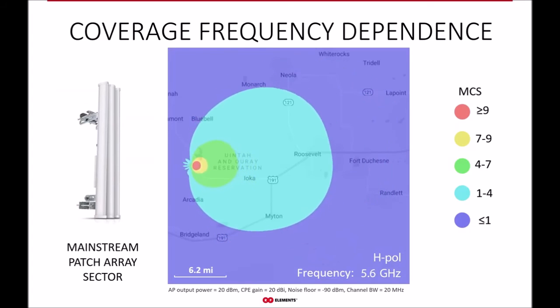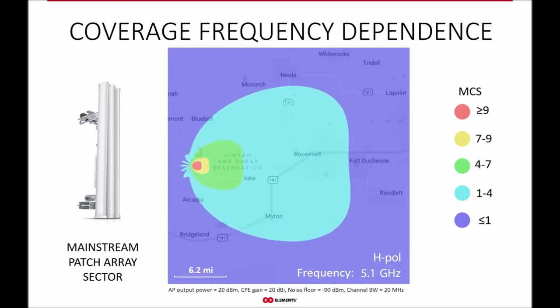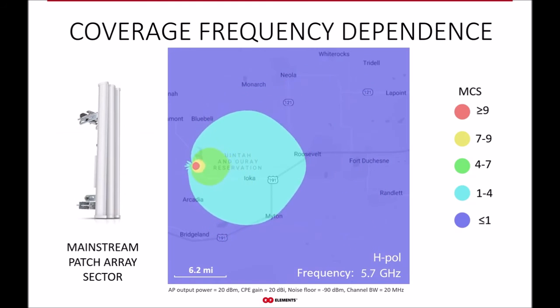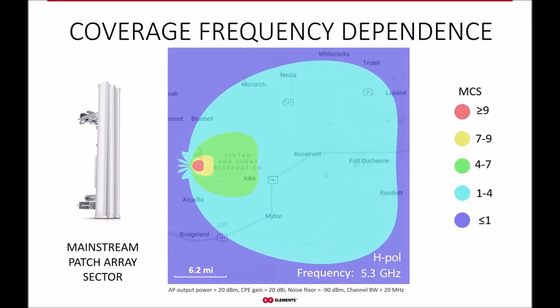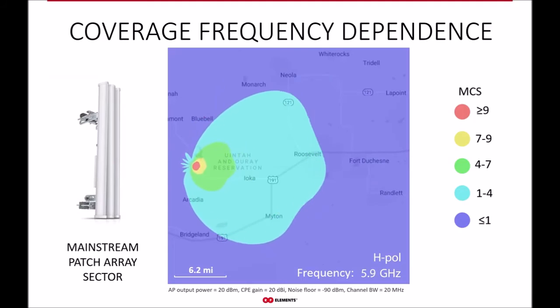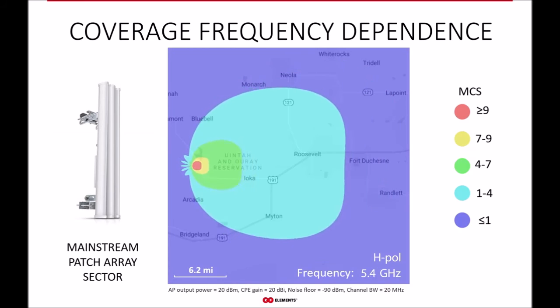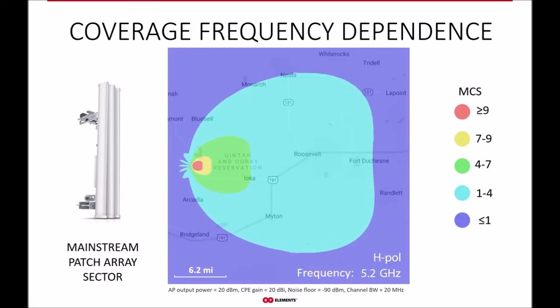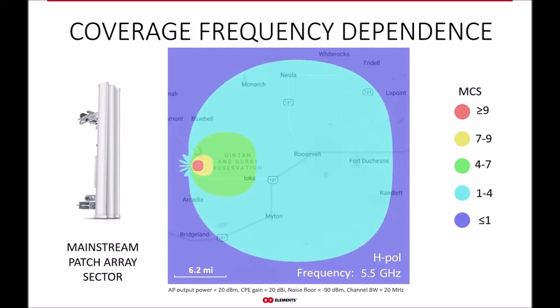Here we show how the frequency instability of the patch arrays reflects on the actual coverage area. Seeing this animation, you might not be surprised, because you probably experienced it in practice: by switching the channels, hoping to use a cleaner bit of the spectrum, the results seem even worse than before, leaving you scratching your head. This is exactly what happens when you change the channels. The radiation pattern changes a lot with frequency, which causes the fluctuations and ultimately unreliability of your network.